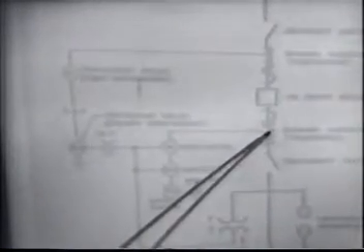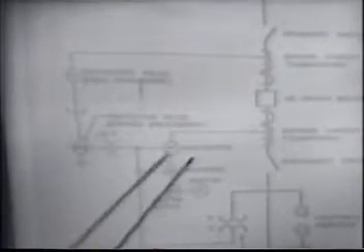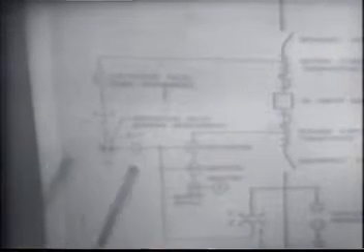And here in the other circuit we show the path of current through the watt meter, through the var meter, the ammeter switch, and the ammeter, and then there are potential circuits to the watt var meters through an auxiliary polarizing transformer to the ground relay.